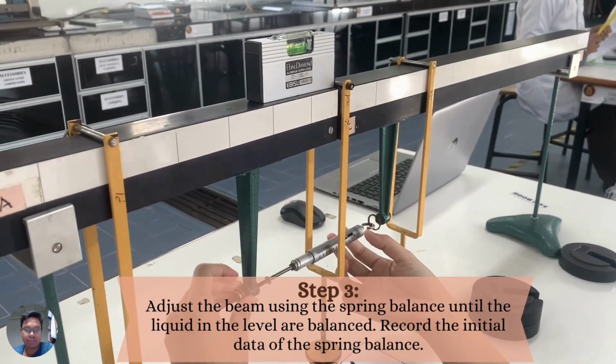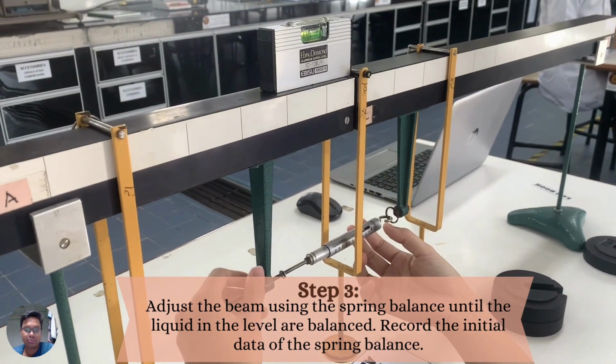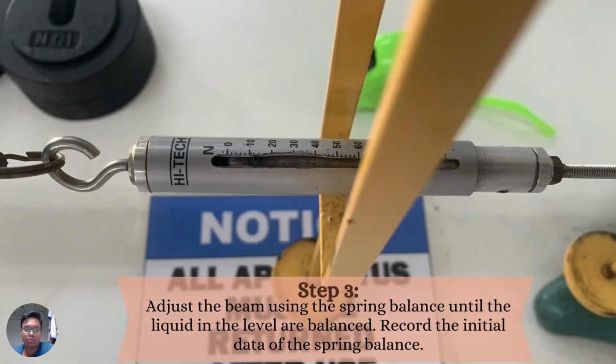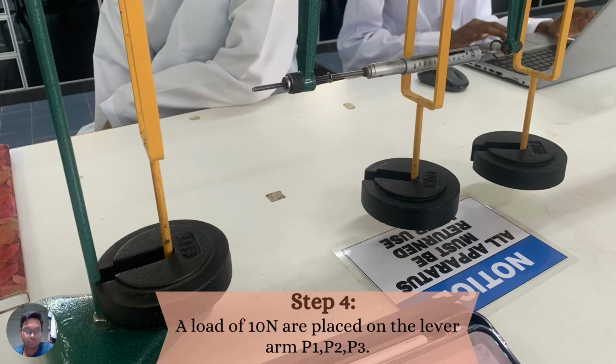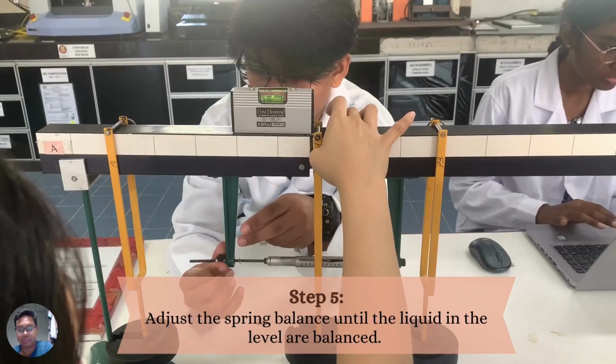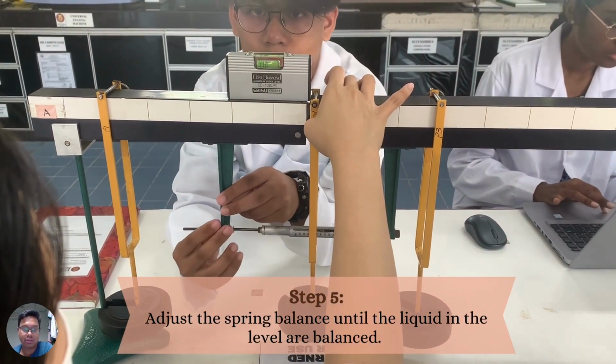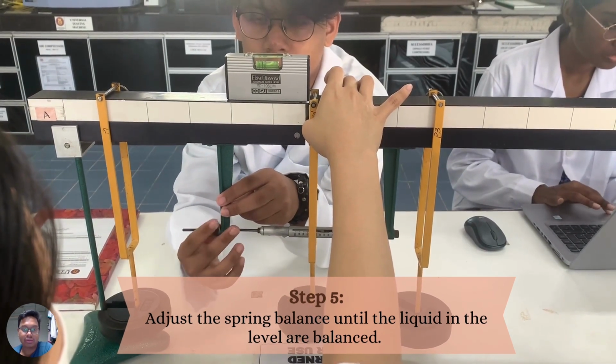Next, step 3. Adjust the beam using the spring balance until the liquid in the level is balanced, and then record the initial data of the spring balance. Step 4. A load of 10 Newton is placed on all lever arms, that is P1, P2, P3. Step 5. Adjust the spring balance until the liquid in the level is balanced.